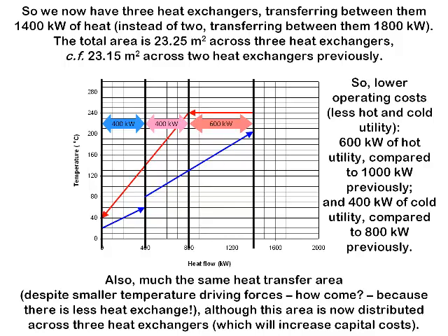So we're doing less heat transfer altogether. We're not doing unnecessary heat transfer, and therefore our heat exchangers are smaller, but the temperature driving forces are also smaller, and so that has a compensating effect. And so in this case, our heat exchangers, the total area, turns out to be much the same.